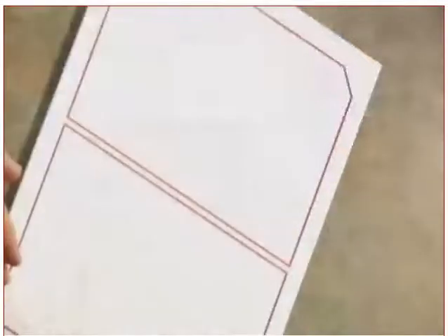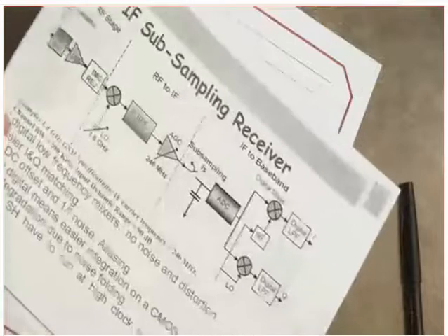Now, so I will do that, and you will see that as long as the sampling rate is at least twice the bandwidth of the passband signal, you will still be able to what? You will still be able to recover the passband signal. Clear? Okay, good.